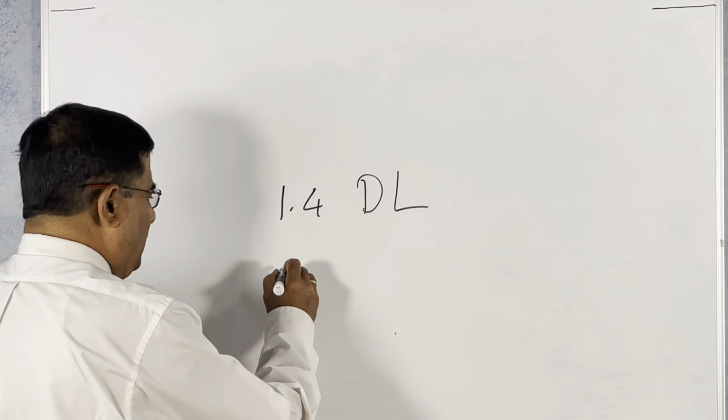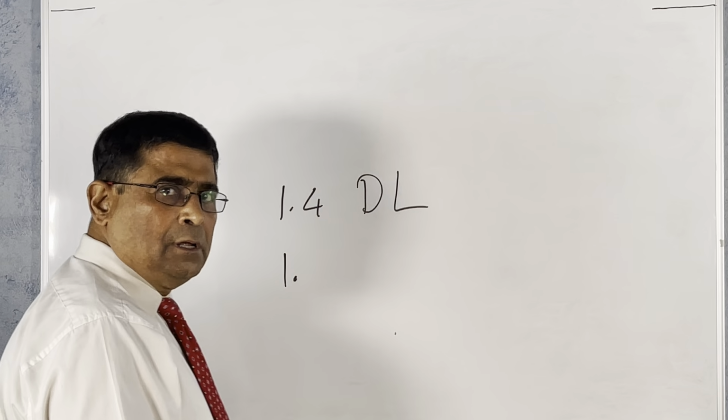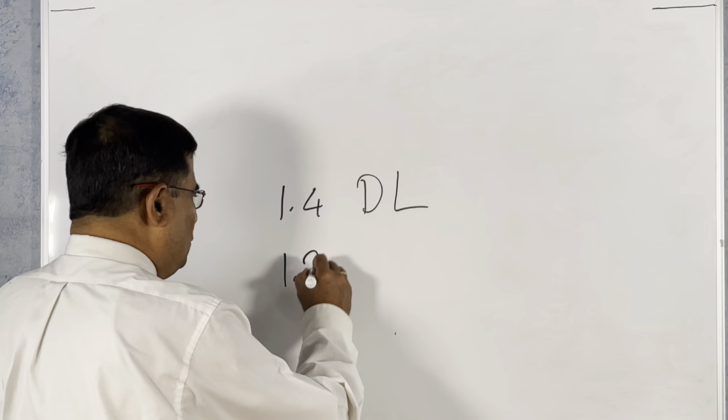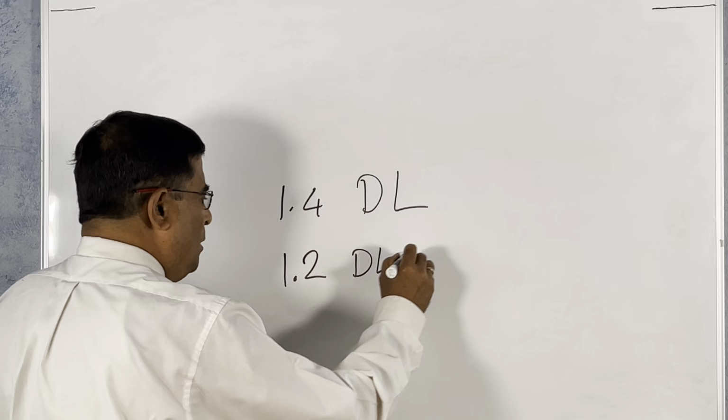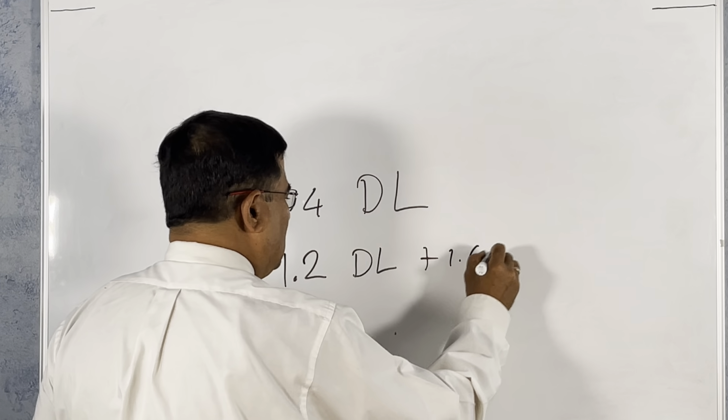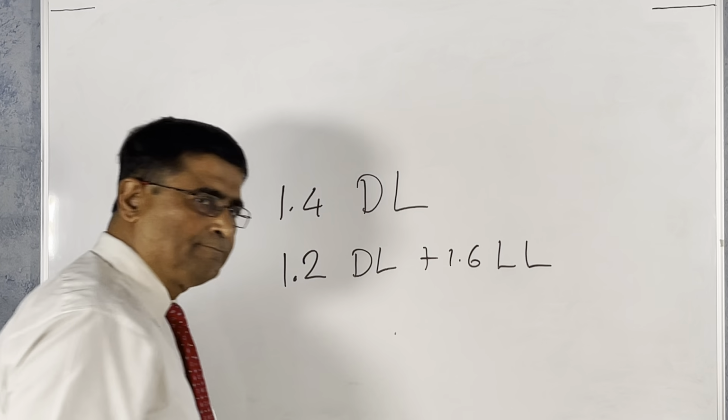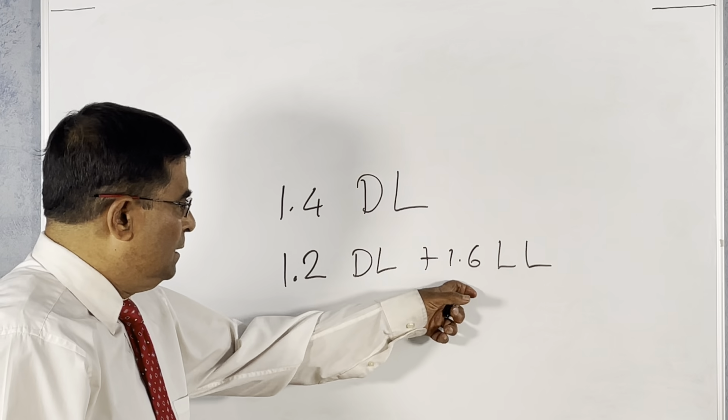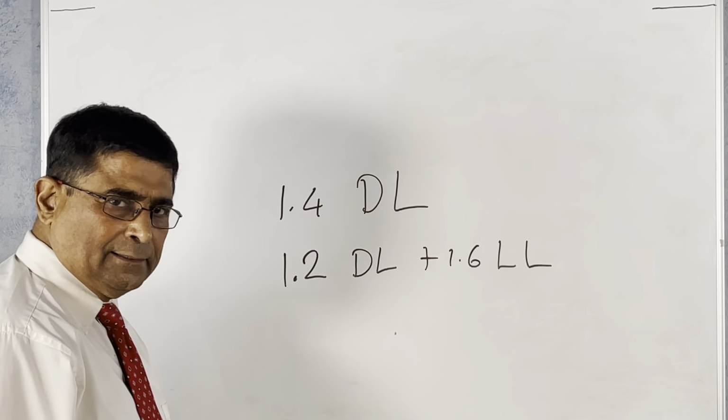But in other cases, if you go with live load, it is 1.2 dead load plus 1.6 live load. See? Not the same 1.5, like that.